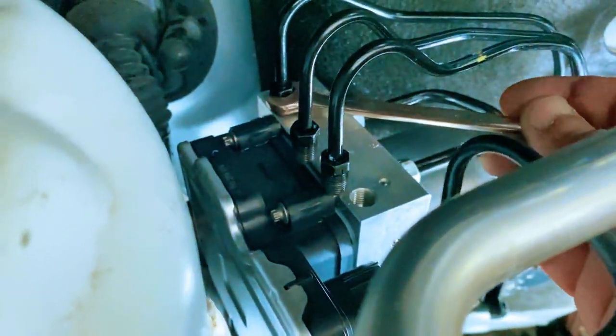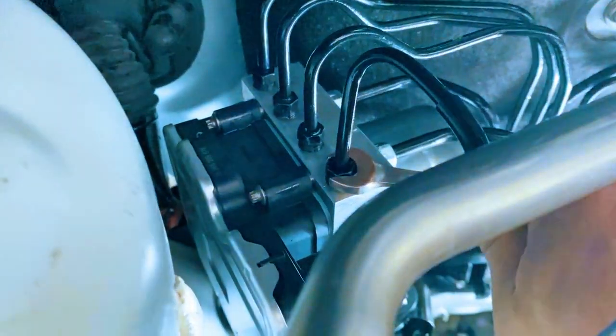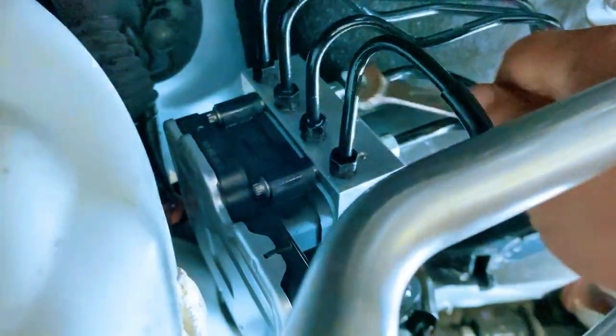7:45. Disconnect the brake lines. Next, we disconnect the brake lines. There are multiple brake lines connected to the actuator, so identification is extremely important. Before removing them, mark their locations or document the routing with photographs. This will prevent incorrect installation during reassembly.